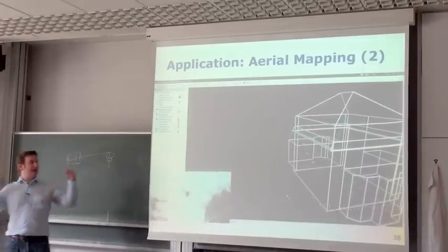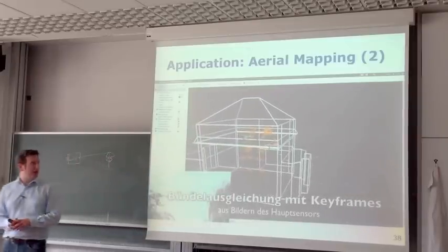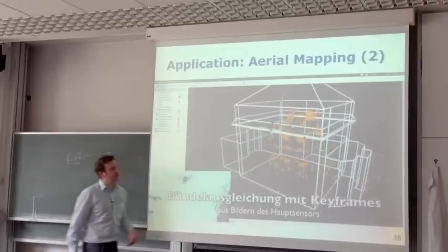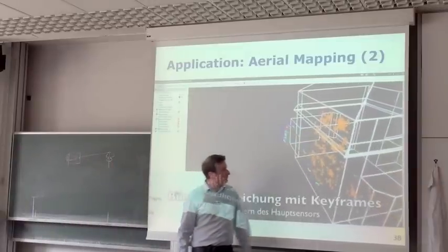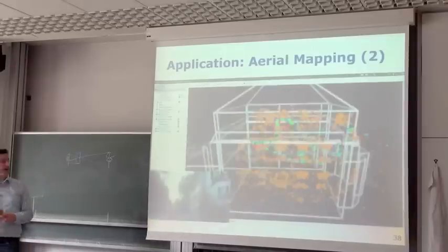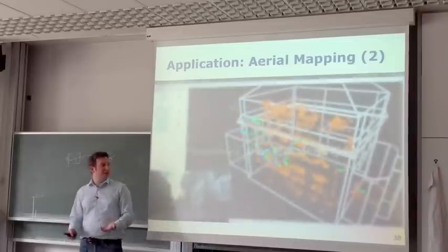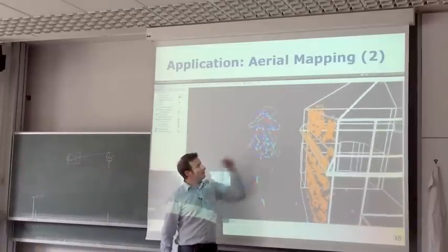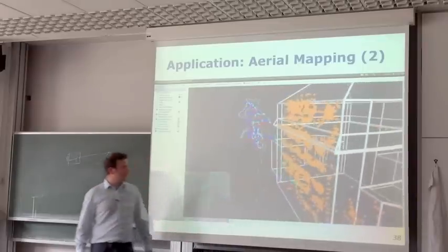And we're extracting features and then doing something called bundle adjustment, or Bündelausgleichung in German, which I introduced before, where we can actually estimate where those points are in the 3D world. We can show that those points are highly accurate, lying on the surface of the building. Using this for building online maps with those flying platforms, we estimate at the same point in time a 3D reconstruction as well as the location or the trajectory of that flying object. You can see here that most of the points are quite accurately aligned on this surface.